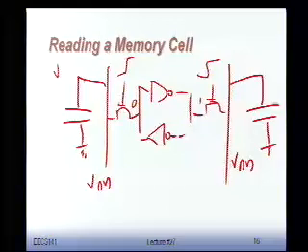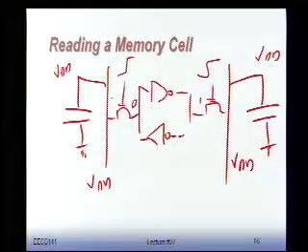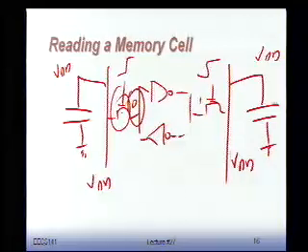For more practical purposes, I almost can consider this as VDD. Okay? So I have a 0 stored here, but I now turn on a transistor with VDD on the other side. There might be a chance that this VDD says, hey, no, if this transistor is too strong, I can overpower this node and pull it back in the other direction again. Right? Because it's not really VDD, but it's a big capacitor with a lot of charge. It looks to me like VDD.